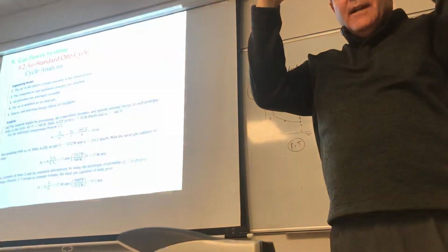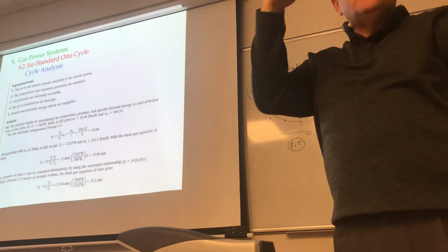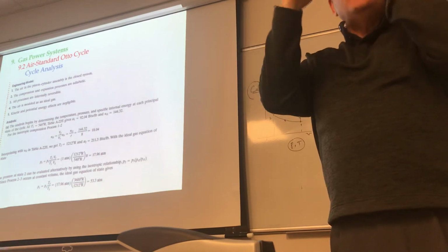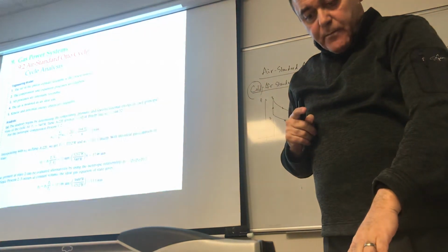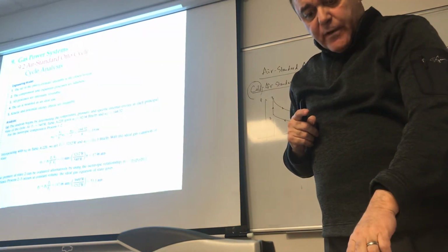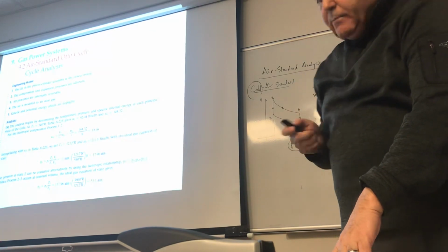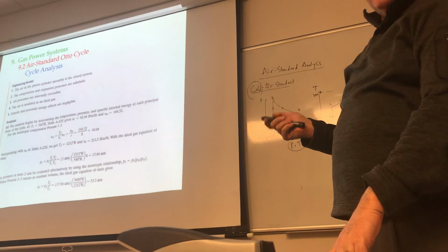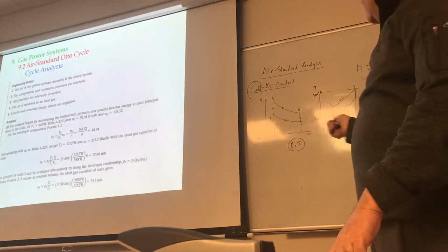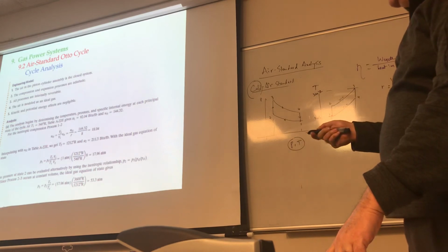It says delta s equal to 0, which means it's isentropic. You only use that for isentropic processes. So for 540 degrees, what is the value of vr? It's 144.32. You just note that: for state number 1, the value of vr is 144.32.